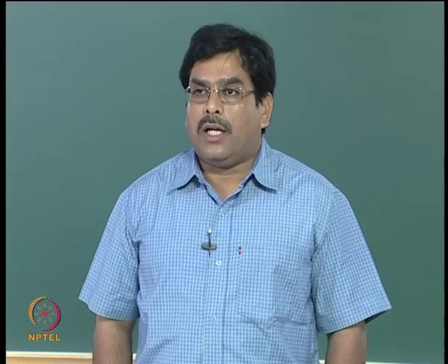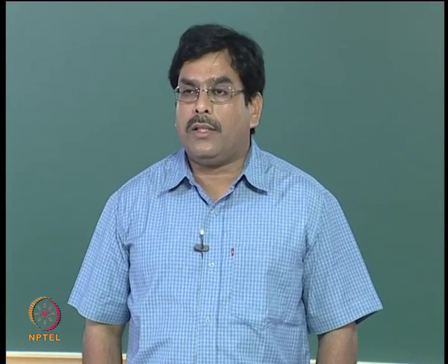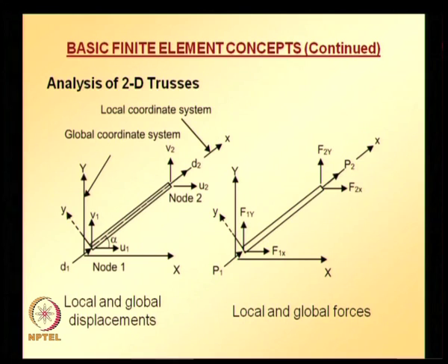Similarly, the force at node 1 in the global coordinate system is denoted using capital F1x, with 1x as subscript, and capital F1y in the global y direction. Similarly, at node 2 we have capital F2x and capital F2y. So these are the forces and displacements.